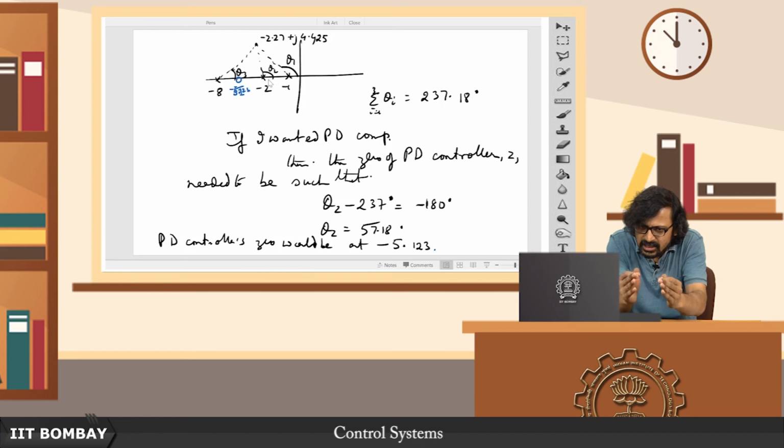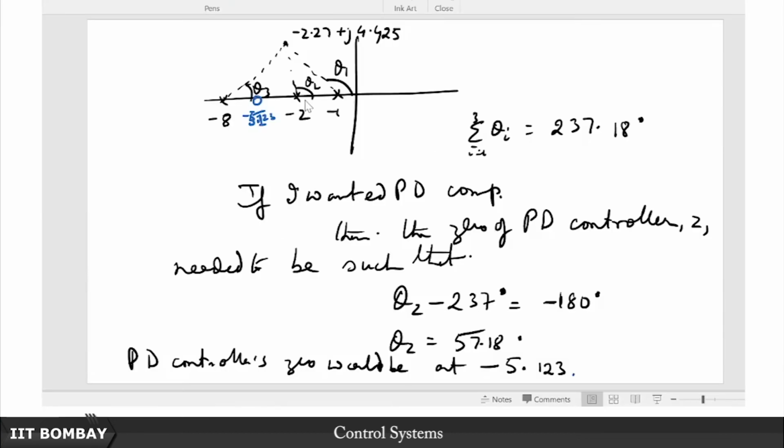Until you go to this last step of verifying using simulations, you'll never really figure out what was best. So do not always fall for this trap of trying to cancel out a pole and zero. In textbooks you might see some examples where they cancel out this pole of the plant using a compensator zero, but it may not always work like a charm like they show you in a textbook example.